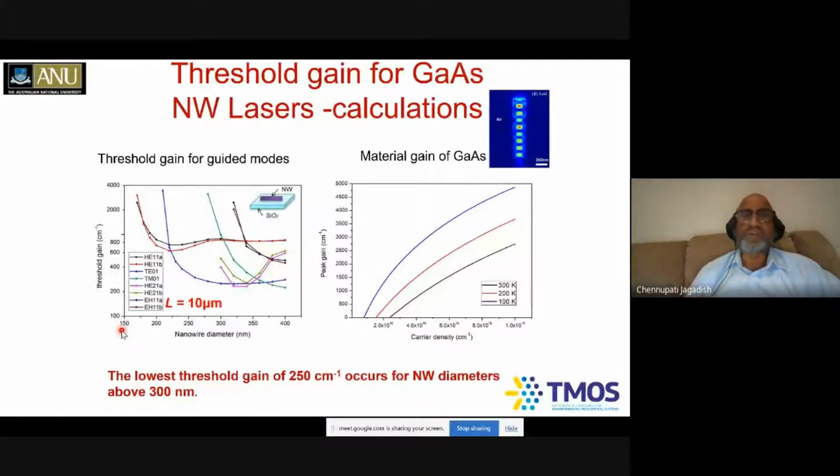If I use, for example, a 50 nanometer nanowire, it may not be a very good waveguide. The threshold gain for lasing is also so high that before you get any lasing, you may exceed the material damage threshold. In the process, you may burn and melt these materials. That's why we started looking at nanowires 250 to 300 nanometers in diameter. This indicates that simulations play an important role when designing these nanowire structures, nanolasers and a wide variety of nanoscale optoelectronic devices.